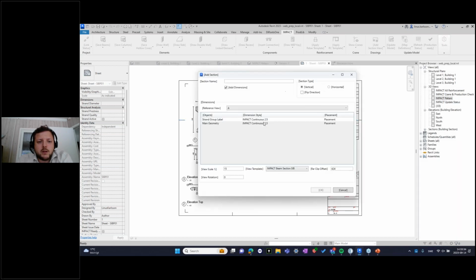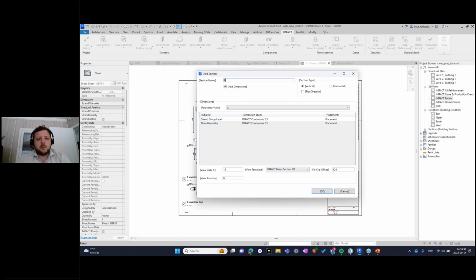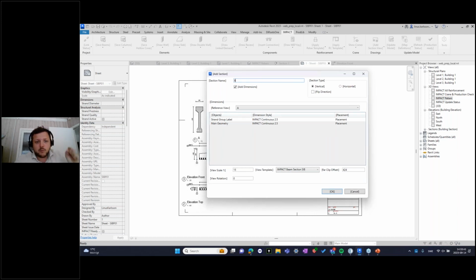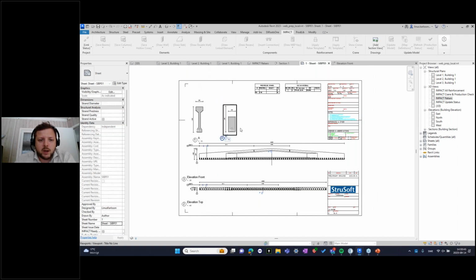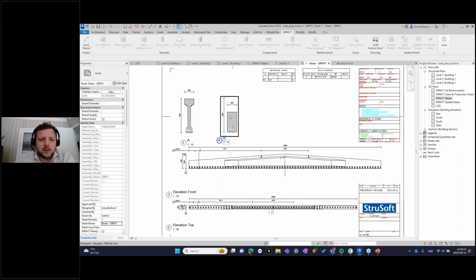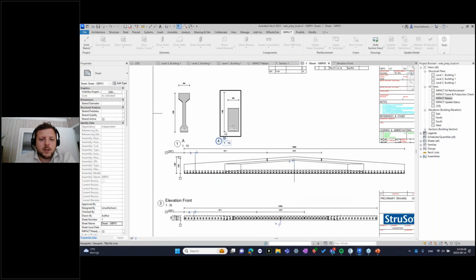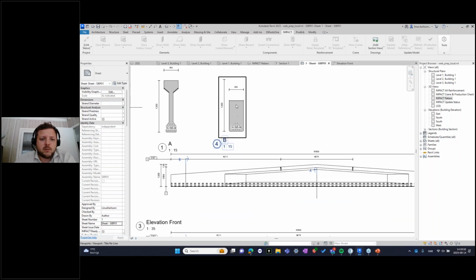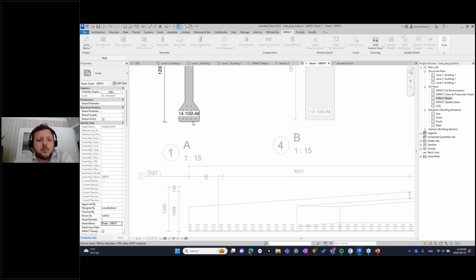It should be placed there and should be named B. Reference A here. So this is the reference. And let's say it's going to be 300 and say OK. So I can see the total height and so on. The reason why I don't see the height from here to here is that I probably forgot to add the setting that puts the secondary dimension.